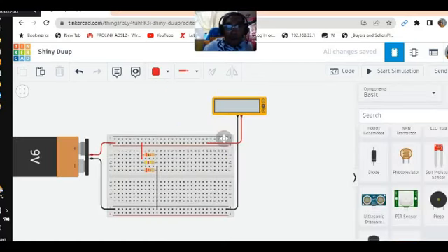Okay, now we are in the Tinkercad software, wherein we decided to construct the parallel circuit based on the problem presented to us a while ago. We have three resistors, 200 ohms R1, 470 ohms R2, and 220 ohms R3, connected in a parallel combination, wherein the first terminals of all resistors are connected together, and the second terminals are likewise connected together to have a parallel connection.